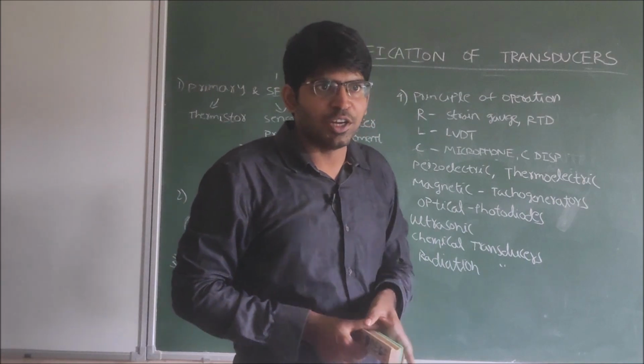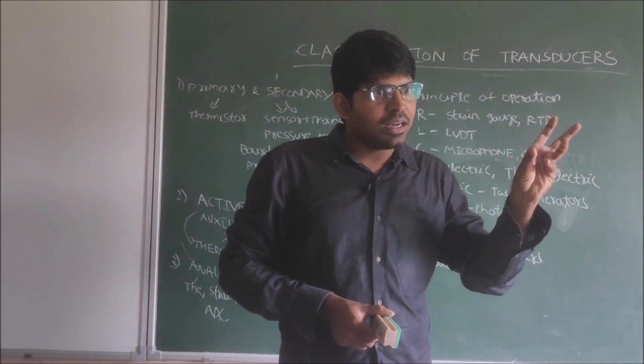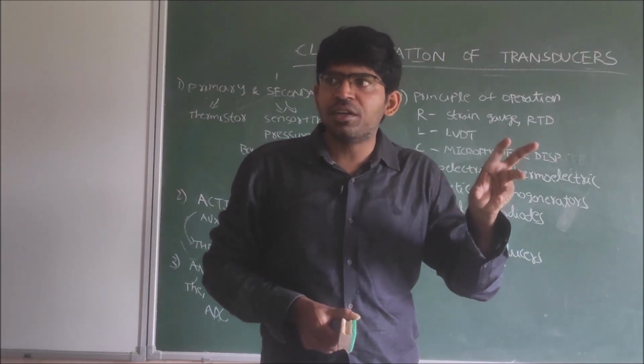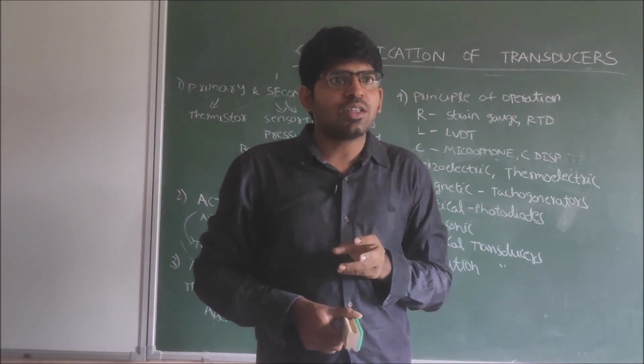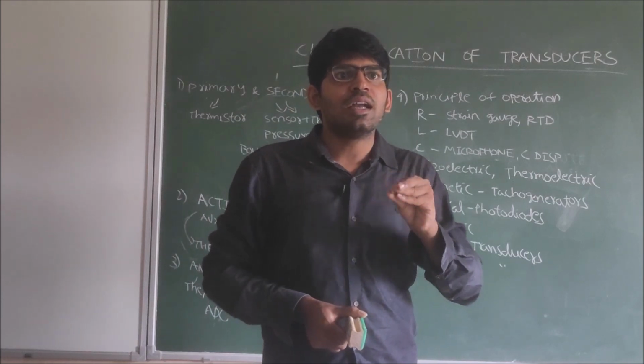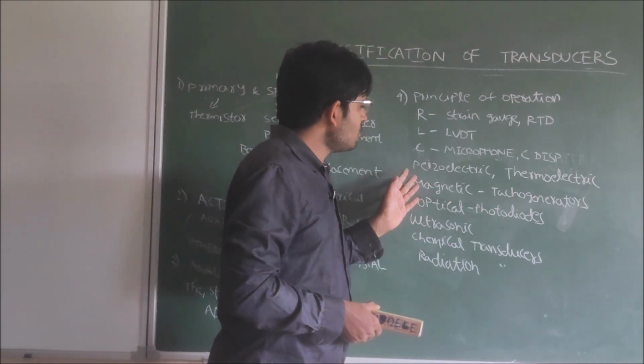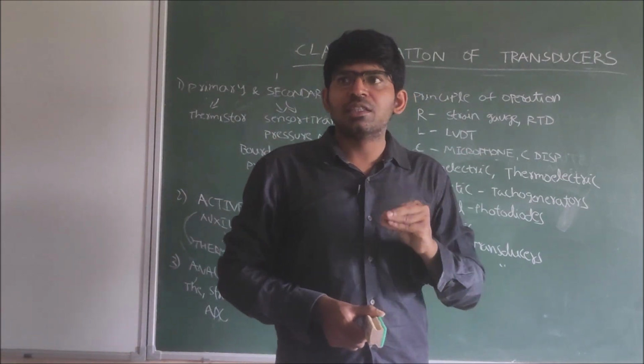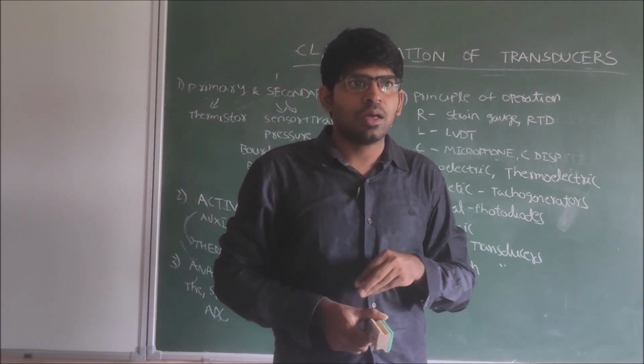Inductive transducers, like the LVDT. When displacement is changing, accordingly the inductance of the LVDT is also changing. That's why these transducers are called inductive transducers. Next are capacitive transducers.